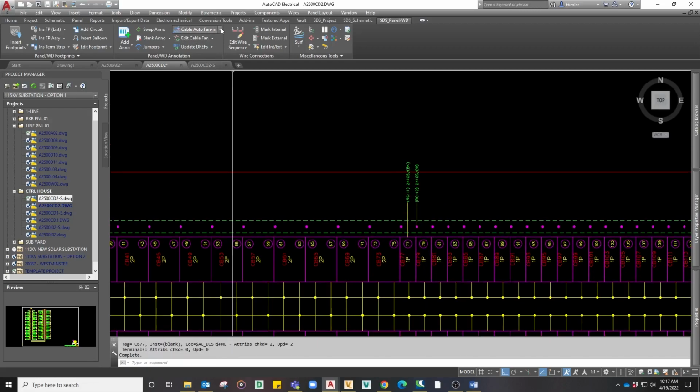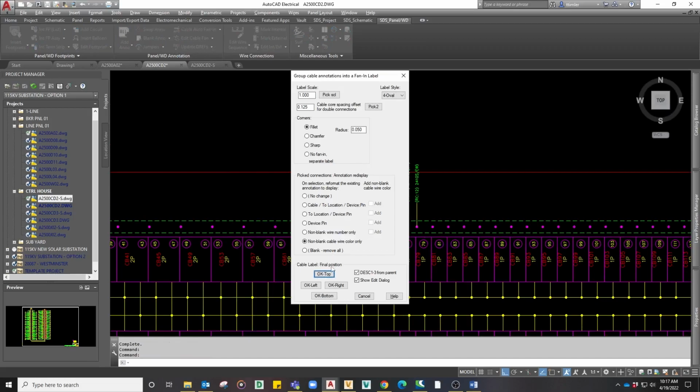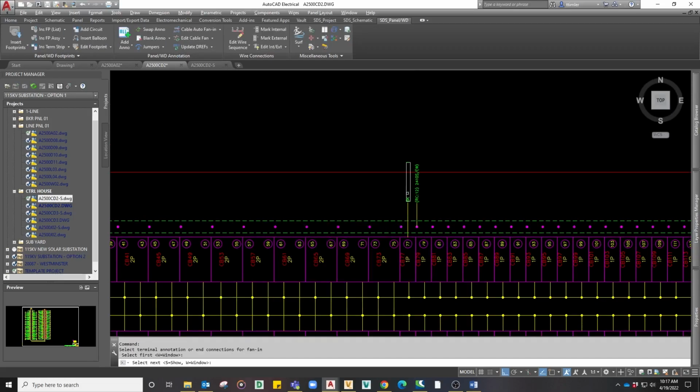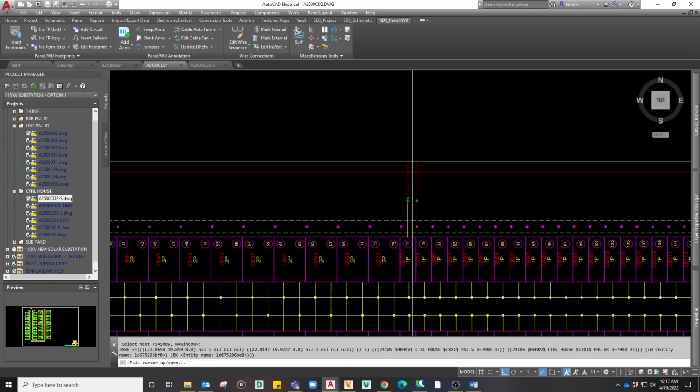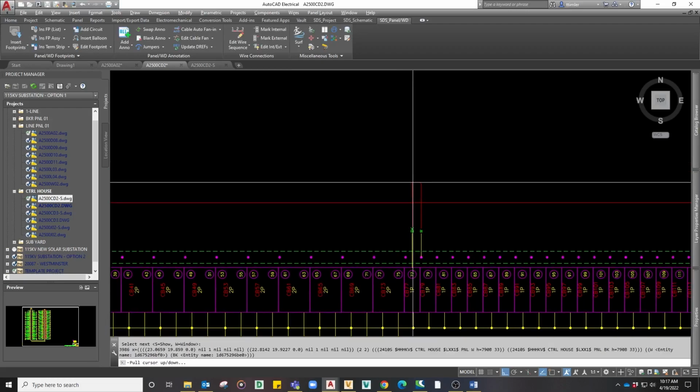The connection diagram cable will momentarily have incorrect referencing as shown in the automatic deref cross-reference information, but that will change after I annotate the other end of the cable.